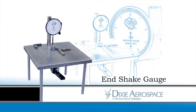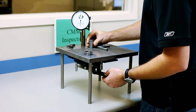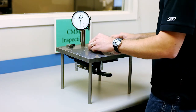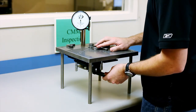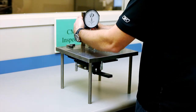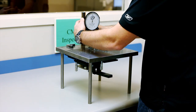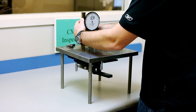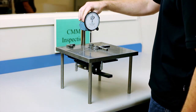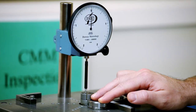The end-shake gauge is a very unique tool designed to measure the space that exists between the roller ends and the guide flanges that hold them in place. This feature can be very critical in main engine shaft assemblies and can only be measured by accurately leveling the roller ends and guide flanges with respect to the dial indicator. After the rollers have been leveled, the machine is designed to control the perpendicularity of the vertical travel with respect to the machine table. This travel is then captured using a high-precision 20 micro-inch dial indicator.